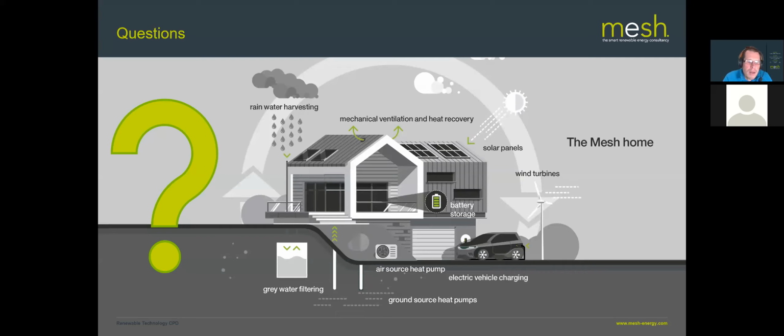Okay, so this is going to be very much a sort of generalities type of thing. Air source heat pump tends to suit smaller properties better than ground source, because a lot of the fixed capital cost of installation of a ground source heat pump can't be made back by its lower running costs. So a ground source heat pump, once it's installed, will have lower running costs than air source heat pump for the same heat output. The disadvantage of ground source heat pump is that it will be more costly to install.